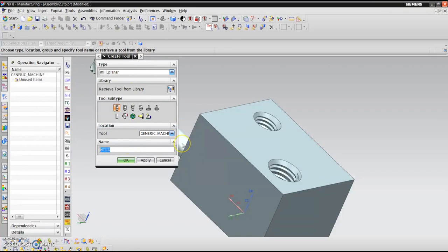Now we need to create a spot drill. Let's do the spot drill. If you are going to use, like we talked about, the point angle, it's going to be a self-centering drill. You don't need to spot it. So in our case, let's use a self-centering drill with an excellent web design, helix design, double margin drill.